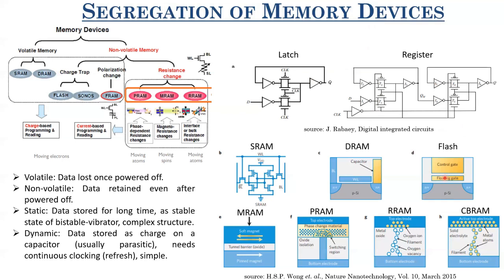So information is stored like this: if it's a 0, then let's say 0 is high threshold voltage such that less current is flowing. 1 is low threshold voltage such that high current is flowing. Like that you can encode logic values to it. That is how it's typically done. So these are some of the mature technologies. FE FETs, or ferroelectric FETs, are emerging technologies. I mean, ferroelectric memories were present. They were commercialized even in the 1990s, but they used different kinds of stacks which were not CMOS compatible.